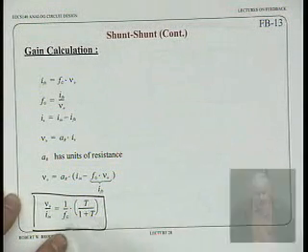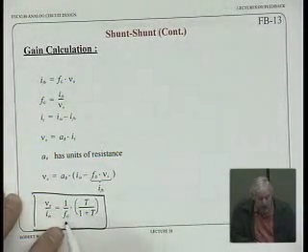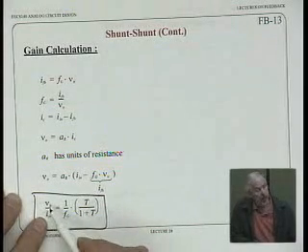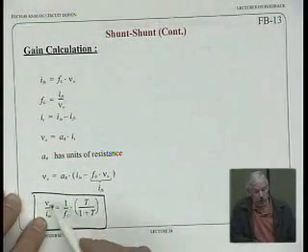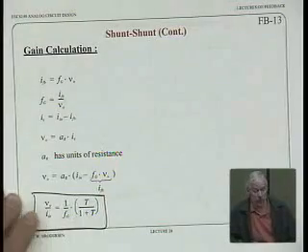So it's exactly the same as we had before. 1 over F times T over 1 plus T, except now this has units of conductance, and 1 over that is resistance, just like we have to have, because the input is V out over I in, right? So we have to have units of resistance in the end. And it's 1 over that feedback factor that gives us those units.